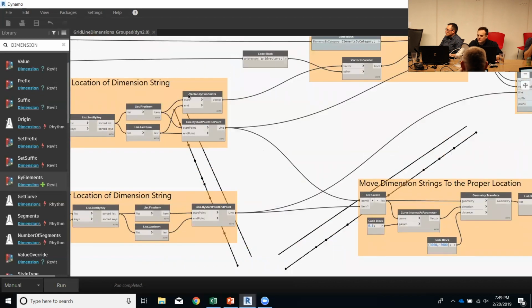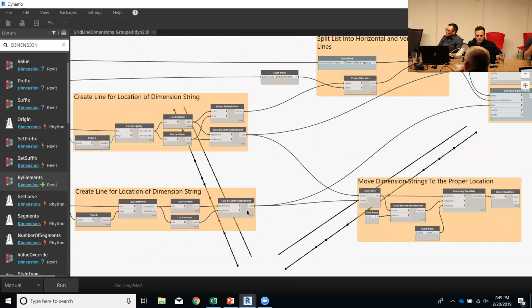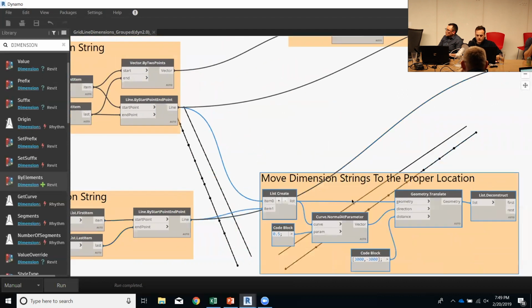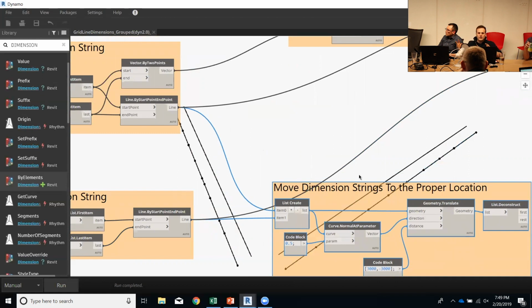Any other questions? So the line you created, is that actual geometry in Revit, or is that just a reference that's not really geometry? Yeah, that's a great question that came up a lot in different ways. Well, why isn't my column showing up in this last definition that we created? Why don't I see a tiny column here? That column is being placed in the Revit model. The line is living inside of the Grasshopper environment. So you're not baking, to steal Grasshopper's language, that line into the model environment.